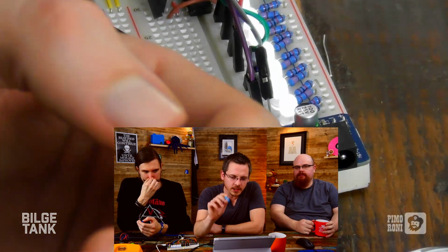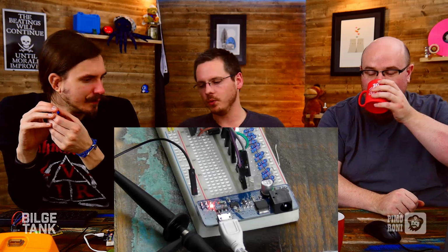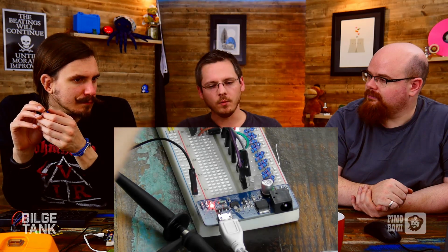Though, having said that, if you're interested in how Delta Sigma ADCs work, the Signal Path blog has a really great YouTube video on it. But basically, instead of having multiple parallel circuits all evaluating a different discrete level, they have a stream of data. It's run on a clock, so you have a sampling frequency, and the output is fed back into the input, and the difference, the delta, is calculated between the input and the current output. What that causes it to do is essentially flip-flop internally, and it gets a stream of ones and zeros, which then go into an integrator, which is the sigma part, which adds up all those values for a specific chunk.